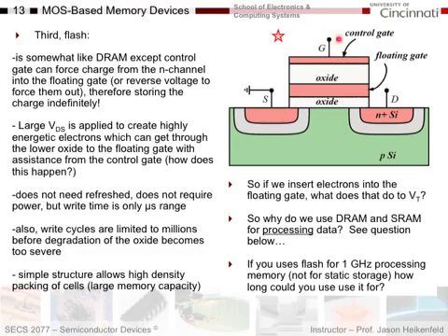And then I'll put a voltage on the control gate to basically try to get inversion to allow current flow from drain to source. But what I'll do differently is I will inject charge into the floating gate, which puts an offset voltage into the input voltage. And so I could have either a little bit of starting voltage to lower threshold voltage, or a little bit of starting voltage to increase threshold voltage by injecting charge in here, which offsets my starting position. Therefore, the amount of current I will get out of this will be much different whether or not I have charge stored and trapped in the semiconductor between these two oxides.